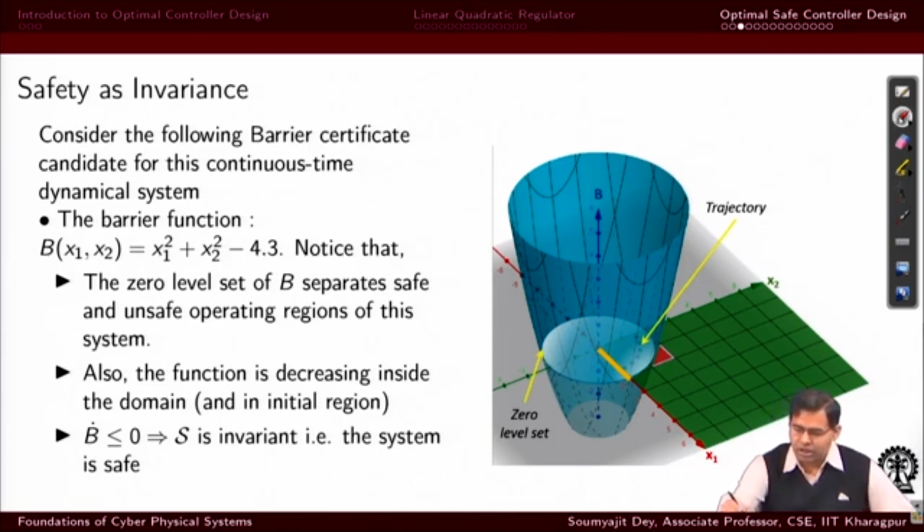So, what we just did, let me just repeat: this is my entire allowed region, the green region. I said that I will let my system belong only inside this region. And how am I doing it? I am defining a barrier function so that my target safety region is contained inside this 0 level set and the sublevel sets.